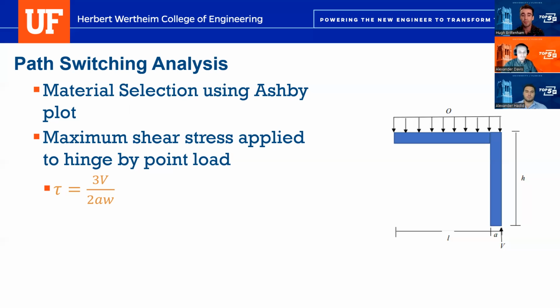With the chosen concept for the path switching subsystem and the material set to be ABS plastic, further analysis was needed to determine how much torque is needed from the ball driver to determine how well the adhesive will hold via a shear stress calculation between the hinge and optical components. Finding a factor of safety in designing for a long life cycle is important to this analysis. On the adhesive website, the strength of the Loctite clear silicone waterproof sealant is 220 psi when properly applied and fully cured on the component.